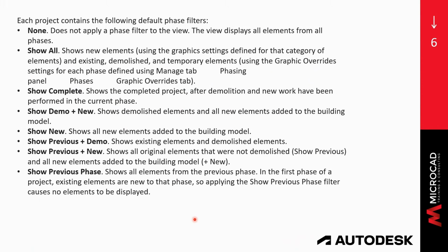Now, new construction, existing and demolished are kind of obvious in what they are talking about. A temporary element is an element that was created in, for example, the new construction phase and gets demolished in that same phase. Sometimes you need to create some supporting walls in that same phase that you know you're going to demolish later. Those are temporary elements.